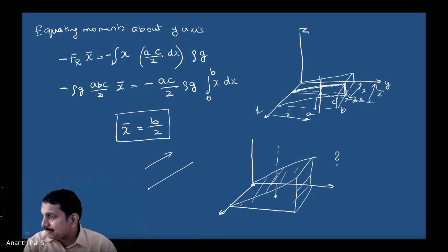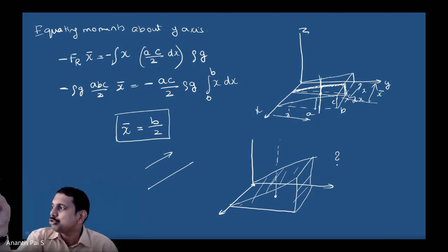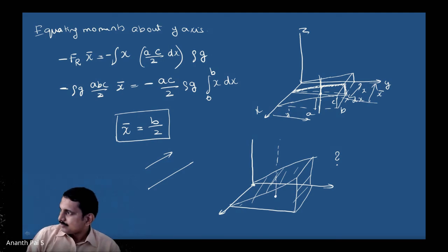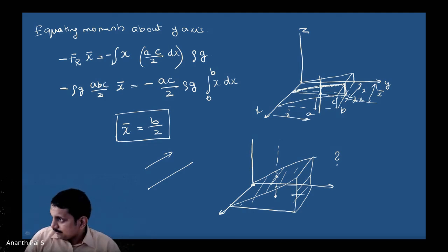And you have to calculate the moment of these individual forces with respect to any point. Thing to be thought about: x bar y bar is fixed, whether the z bar should be in the middle, or should we do it below here, or should we do it above? These are the questions, or somewhere other point. Because equivalence means it should create the same turning moment at every point.